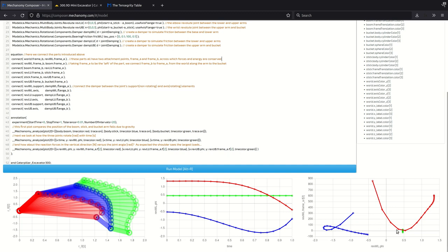And we see them in the canonical directions of X, Y, and Z. And this is just the start of the analysis, because what we're able to see here is that the forces are strong functions of the joint angle. And in an excavator, many of the bearings don't make full revolutions. And what that means is that the bearing should not be designed expecting continuous revolution. Instead, some parts of the bearing are going to see much greater loads than other parts. And this graph is a first estimate of those loads and where they occur under some generic trajectory.